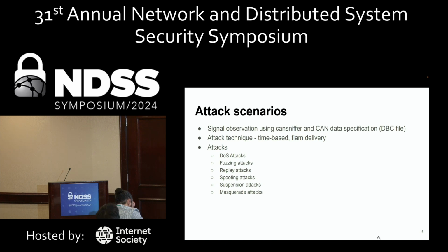Accordingly, we used DoS, fuzzing, replay, and spoofing attacks during our experiment. But suspension and masquerade attacks in our dataset were simulated due to their complexity, requiring expert hacking and comprehensive vehicle knowledge. We simulated the suspension attack by removing legitimate target ID frames for a specific period of time. On the other hand, in masquerade attacks, we removed the legitimate frames and only kept the malicious frames during the attack.